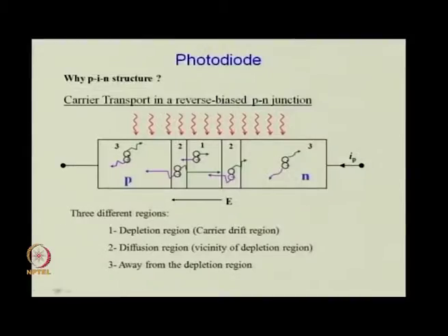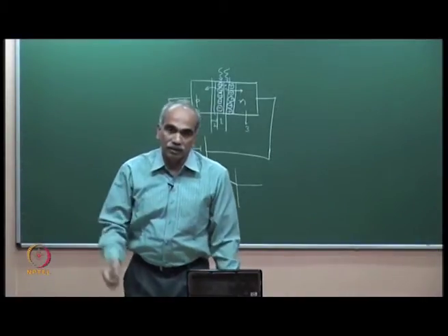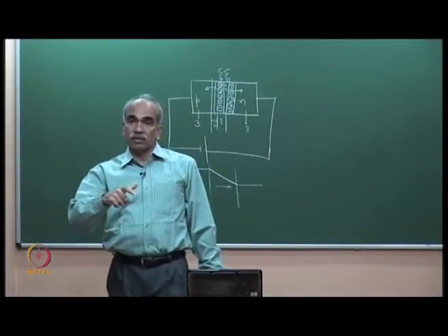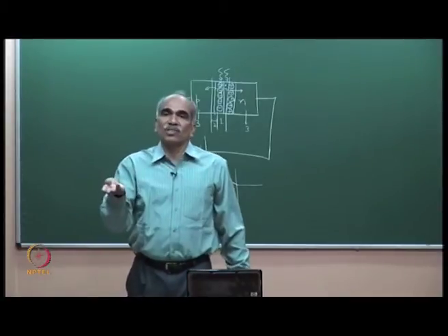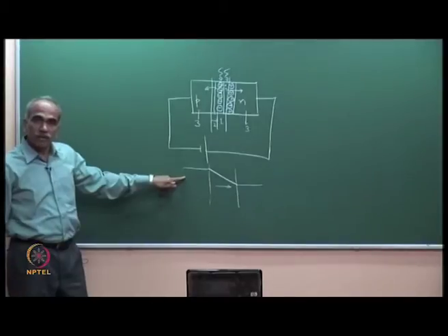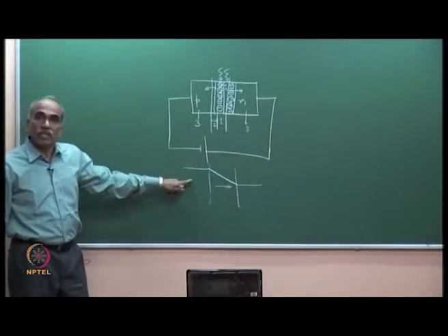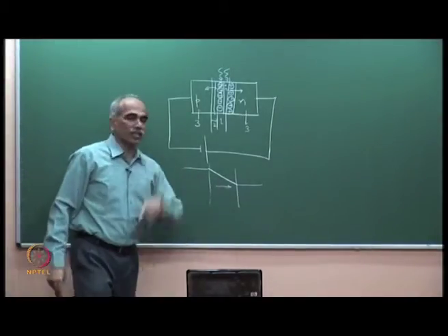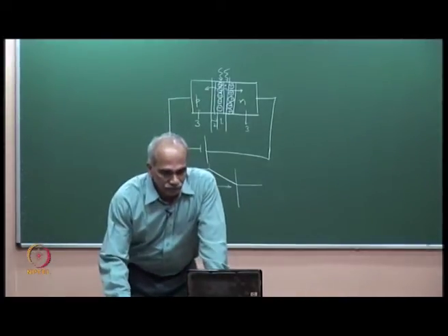And far away from the depletion region, where there is no field, there is a potential but there is no field, that is dV by dx is the field. There is no change in the potential there, it is flat. As you can see, the potential energy is flat, and therefore there is no field. Field is only at the junction region. Therefore, this is the drift region.